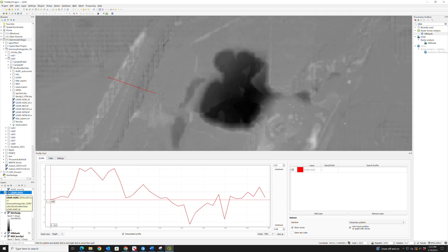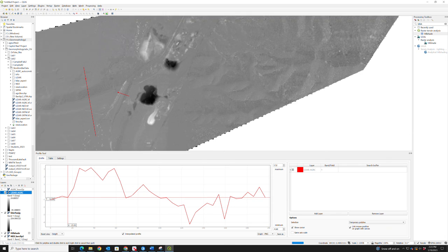So if one of the data sets is off just slightly in an east-west sense, the hill could be shifted over. So then one side of the hill valley could be positive change and the other side could be a negative change. And so that's another thing to worry about when vertically subtracting the different data, is whether or not the coordinate systems are really truly matched up to begin with.